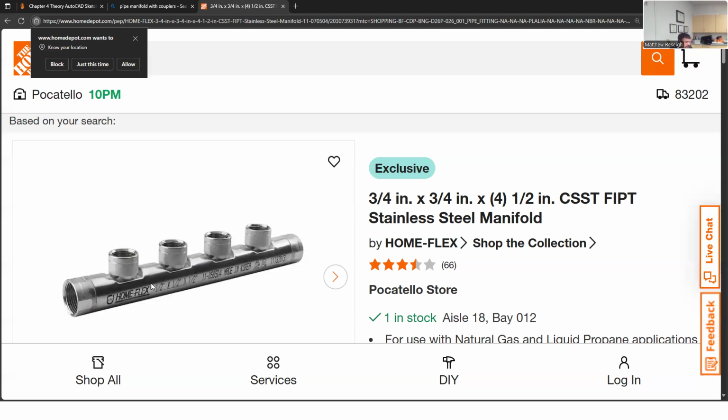If you have a sprinkler system, likely your house supply comes out to a manifold and some valves that can control each one individually, and it comes into a manifold like this and then distributes from here to the zones of your house. Generally, when you water your yard, you can't run it all at the same time. You break it up into, you know, 6 or 10 sprinkler heads, depending on how much they flow and how much pressure you have to distribute water to a zone.